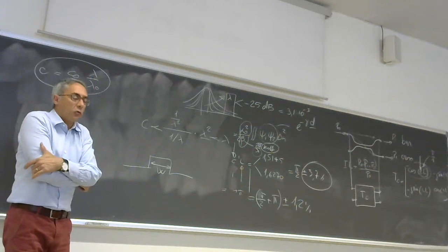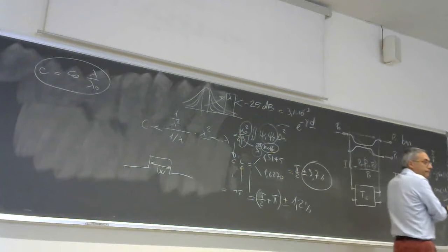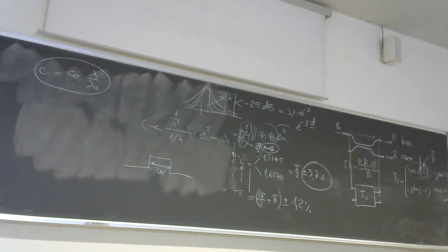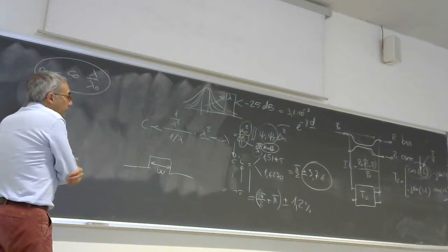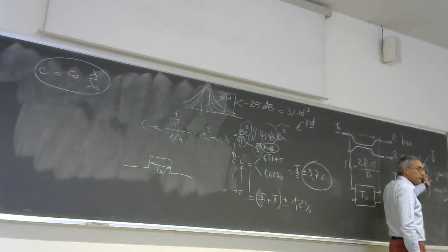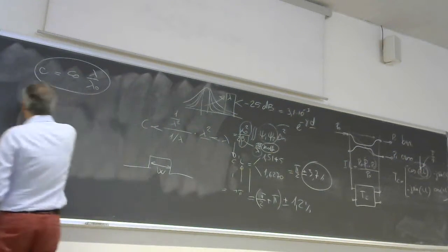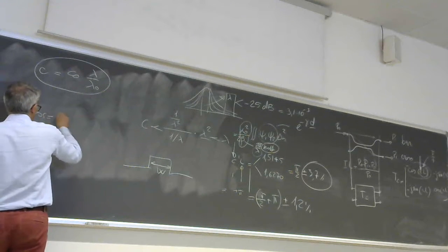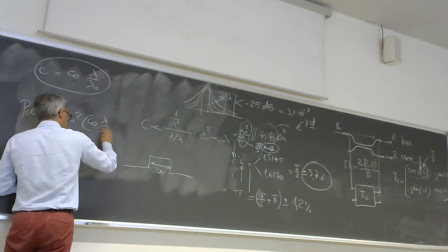This is nothing strange. We have to expect that the coupling coefficient depends on the wavelength. You accept, right? So it means that the transfer matrix, the behavior of the coupler, depends on the wavelength. So the P cross, for example, is sin square of this expression.